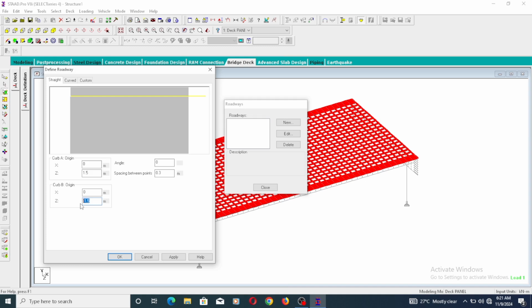All right, so let's go ahead and do that. Okay, so now we've created our carriageway of 8 meters with pedestrian walkway. This is the center, so we have pedestrian walkway of 1.5. So I apply it, and I will okay. So you can see that we've gotten our walkway carriageway seed 1W. So it has been created. The information is here, so you can see the information in this dialog box. So we are going to say okay.